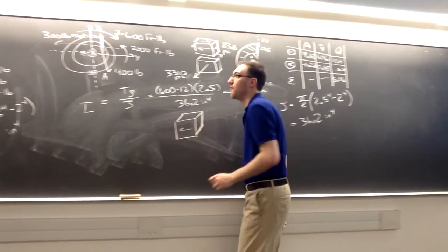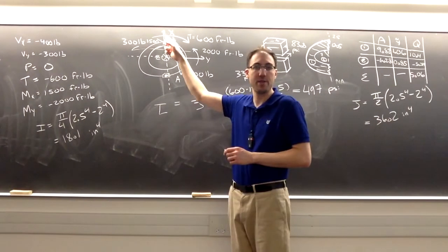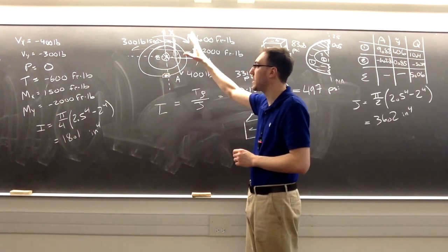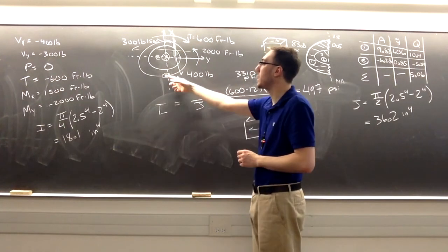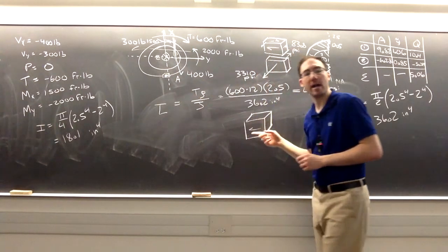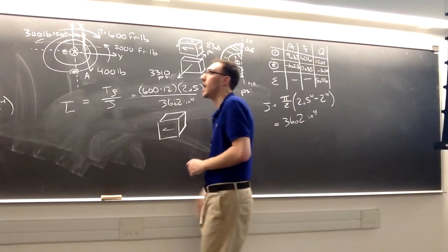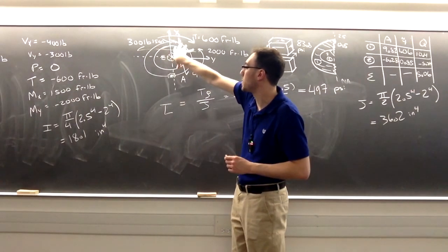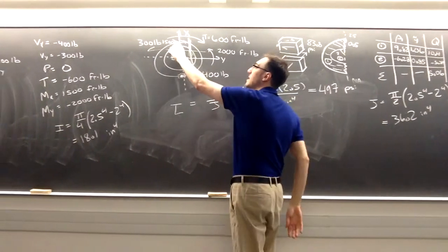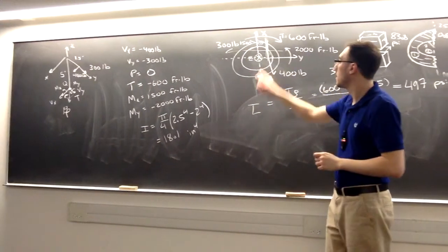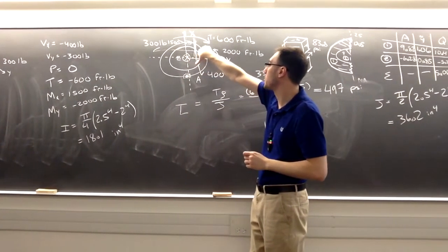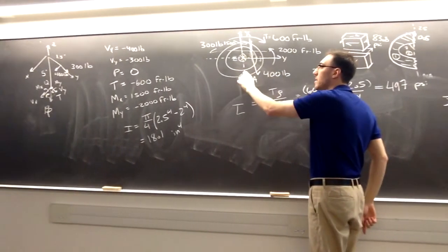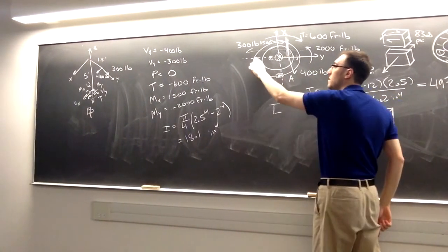So why is that? If we look at the way the torque works, which is different than the others, well, the bending stress also changes. But depending on where this is located, that direction of stress is going to change. Because at the top, that twisting that's twisting it this way and shearing it this way is actually going to be in this direction. If it was an element down here, now the torque is pulling that piece of it down. It's pulling this piece of it to the left, this piece up.